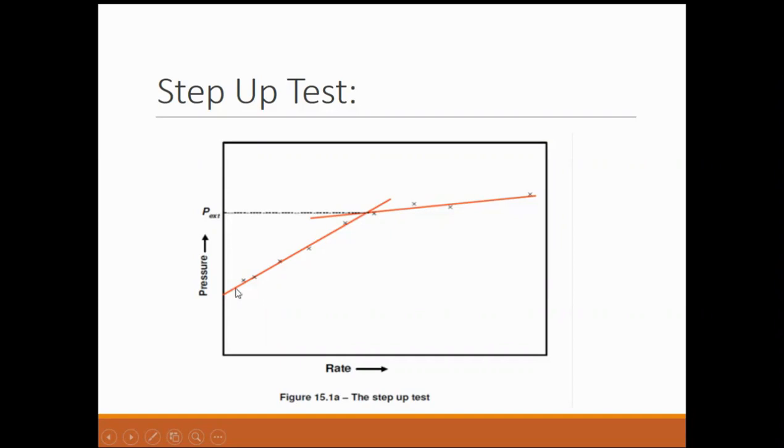So there is something called a step down test. The result of it is also a graph of pressure and rate. If the graph is concave upwards or convex, it is called tortuosity dominated. This is the analysis of friction, the kind of friction that the formation is having.